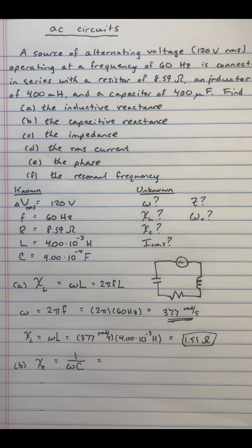And there's a similar sort of thought process here very quickly. A capacitor also has something akin to a resistance, right? As you pile more and more charge upon a capacitor and upon the plates of a parallel plate capacitor, for example, what's happening is that those charges are giving you a reaction or resistance to putting more charges on it. And so we have, again, something that's akin to resistance. But again, it's not resistance in that there's no energy lost. So there's no thermal energy that we generate that way, at least in ideal circumstances. And so it's not a true resistance. And so again, we call it reactance. The capacitor is reacting to the presence of a current.